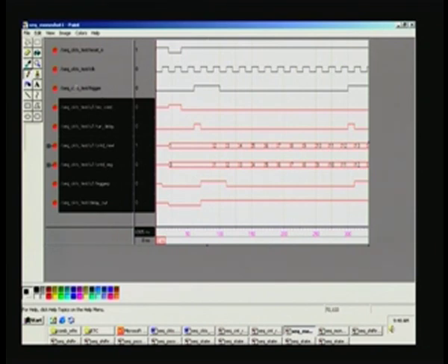The current trigger value is here, and whatever is the current trigger value will be pushed as the previous trigger value for further processing, namely to find the rising edge of this trigger. That is the reason why we preserve this. We preserve the current value of trigger and then use it in the next clock cycle. Is that clear? That is how you sense the rising edge, and for the run delay, for the time being I will just say it is counting 1, 2, 3, 4, 5, 6 and so on, and not much information here, and we will come back to it.